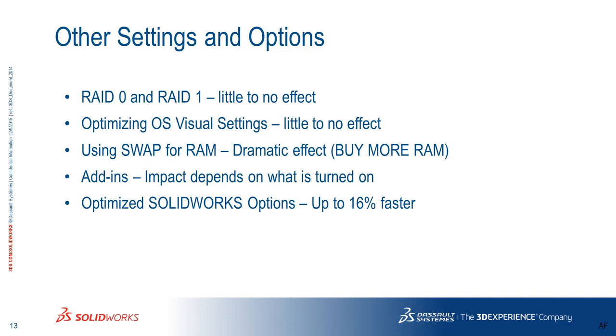Now, other things we've tested in the past that we're quite fond of. We tested RAID arrays, RAID 0 and RAID 1, mirroring and some other aspects of it, so that we could determine if writing and reading from 2 disks simultaneously helped SolidWorks performance. It had little or no effect in our test. Little or no effect. Not a lot of people are trying it anymore, so we don't test it anymore.